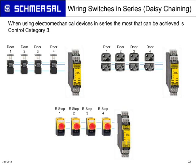But if you opened up any of the other doors, 2, 3, or 4, either at the same time or after the fact, and even before, that failure goes undetected. You can clear the failure out of the system. So there are certain faults that may be detected or may not be detected in a daisy-chained type of system.